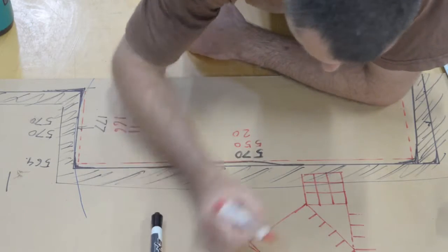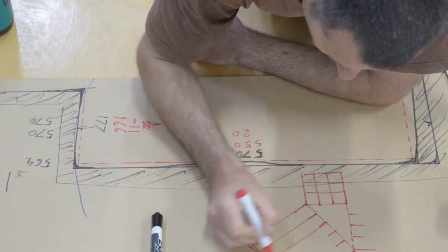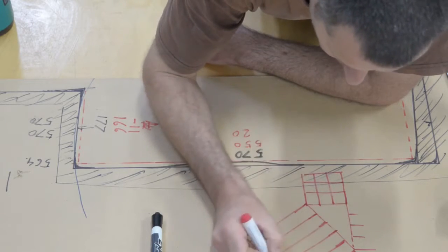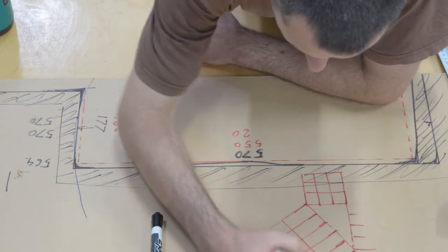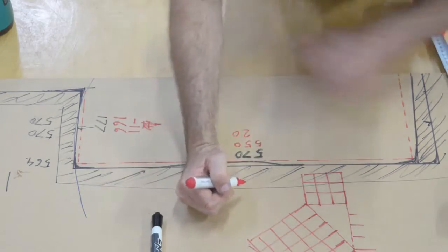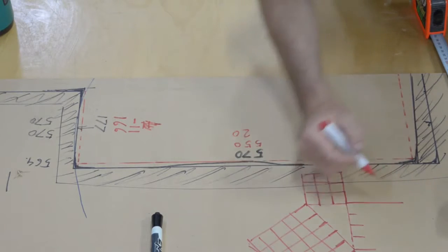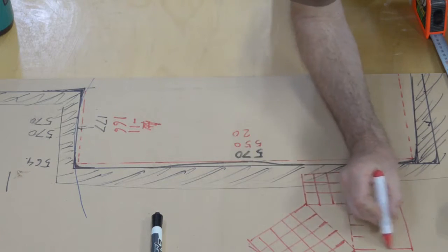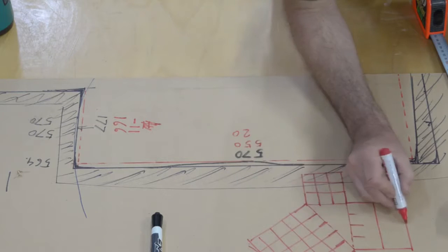Now 3, 4, 5 is a handy number to use because they're quite simple numbers, and it doesn't matter what kind of unit you use. If you remember 3, 4 and 5, you've got yourself a measuring tool for square.